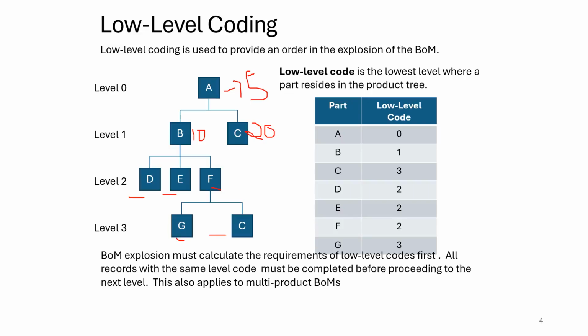So in this manner, the MRP is calculated in a top-down fashion, where we first calculate what is the requirement for the entire assembly A. Based on that number, we go all the way down to the bottom level of this entire MRP chain and calculate what is the required number of parts C to get the number of assemblies of A that we need.